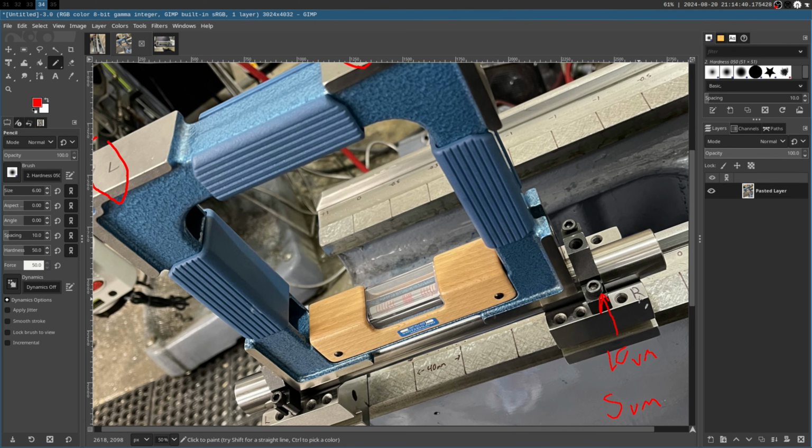That is the concrete floor and gravitational effects locally changing, right? Like think about it though. This is sensitive, right? Under the 20 centimeter base of this level is sensitive to 10 micrometers across the base, right? So if this gets 10 micrometers higher, it will move one division. Now, think about how crude a concrete floor is, right? If a crack forms in your concrete floor, one side probably got higher than the other, right? There's some stresses, and this probably shifted up and this shifted down, right?